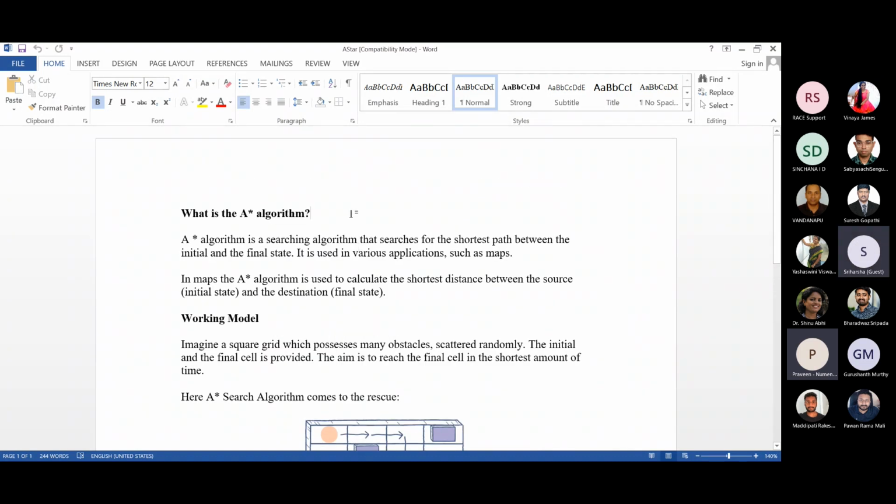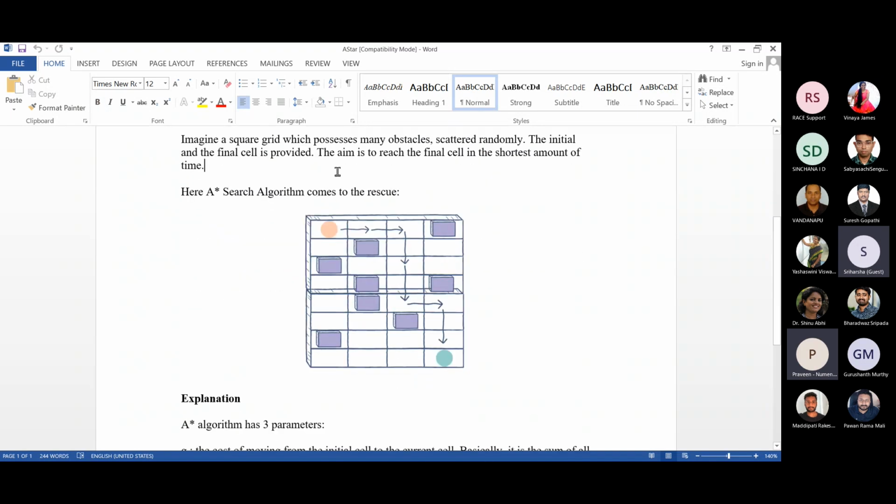The optimal path from source to destination is obtained using the open set of intermediate points, and the selection of open set intermediate points is based upon the cost, derived from the underestimates and overestimates of the distances between the open points and the destination, and the open points and the source. That is an application of the A star algorithm.